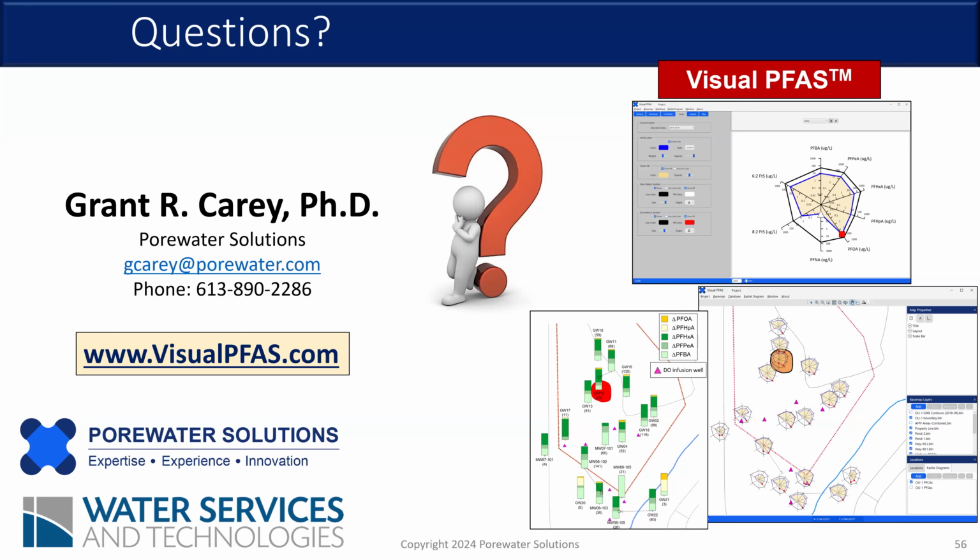Perfect. Okay, and another question: what formats are available when exporting radial diagram maps, and can these be imported into AutoCAD or GIS for final figure polishing? Yeah, so you can export first. You can print to a printer or to a PDF file, and you're printing basically that one-page base map when you do. Or you can export electronically to Surfer BLN files or DXF files, which you can then use to import radial diagrams and stack bar maps into your figures that are either in AutoCAD or GIS.